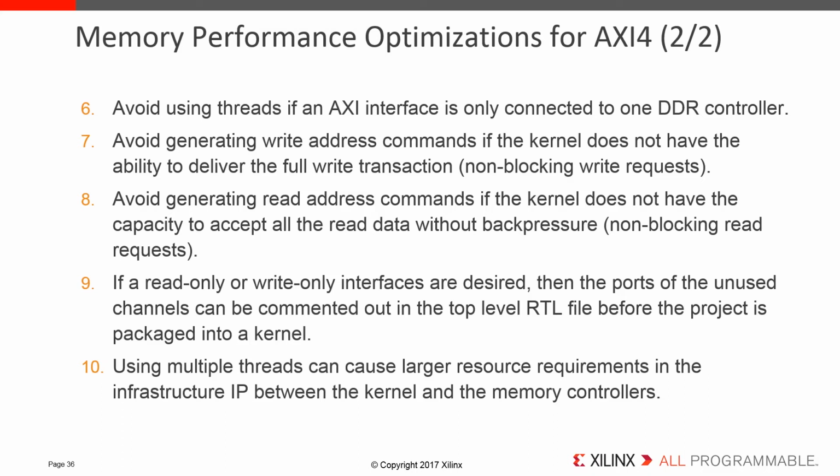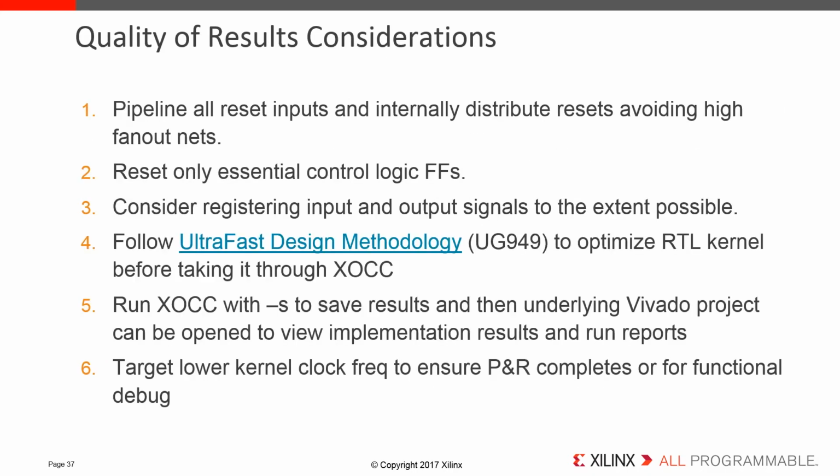Try to avoid blocking the memory controller by requesting data that it cannot accept or generating a write transaction where it cannot deliver the data. And explicitly declare read-only or write-only interfaces. This will save logic.